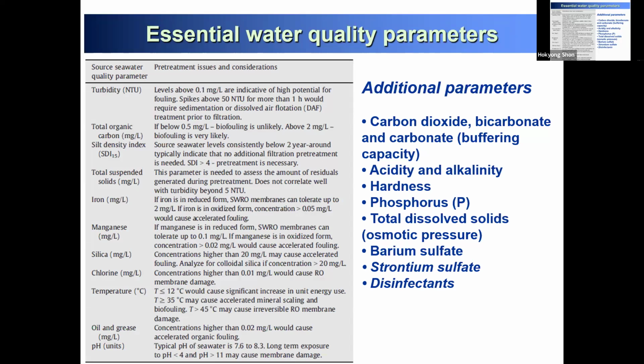We only like to focus more on temperature, I think physical, and also osmotic pressure, because we can easily calculate the recovery. Seawater at 3.5% has an osmotic pressure of almost 28 bar. I want to recover almost 50%, so the osmotic pressure doubles, meaning 7% concentrate.